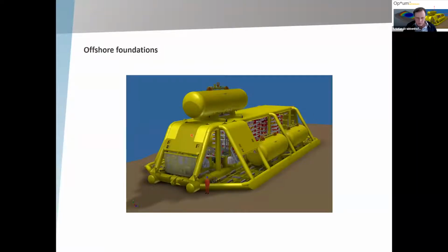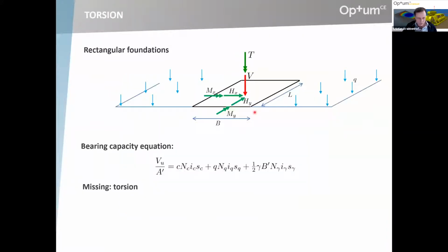Well, for these large offshore structures, I've been told that one of the load cases is the case where a trawl or a fish net gets caught at the corner of a structure like that, and that of course generates vertical force, and could also be some uplift. I think that comes with this trawl load case as well, and then some torsional moment if you refer to the center of the foundation. So that's one example anyway of where torsion comes in.